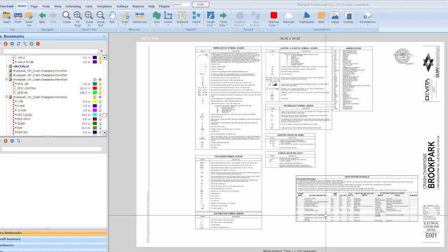The third thing that makes completing an electrical estimate really difficult is determining your wire and conduit totals for branch circuitry for your power plan. If it's not already noted on the plan, sometimes they'll note it on the construction docs, so you just follow the lines where they lead you.